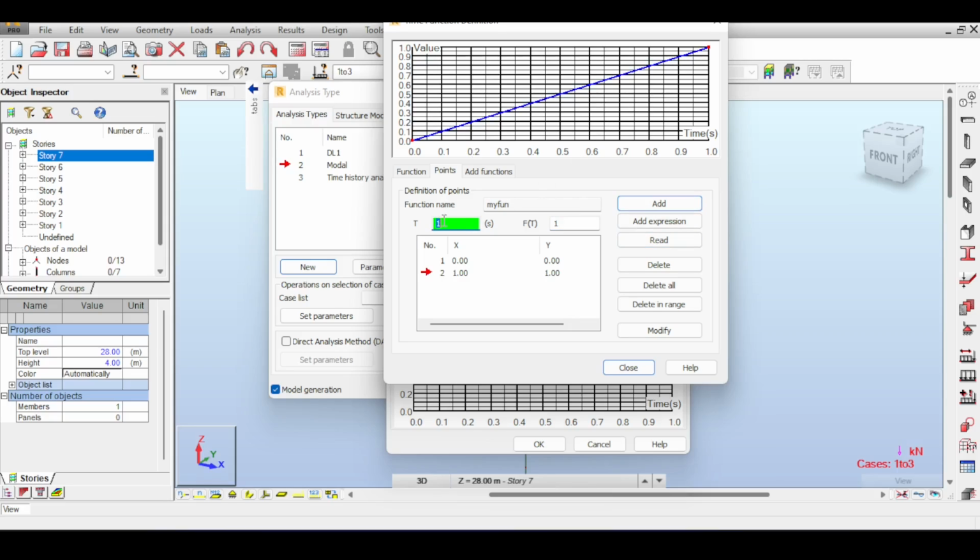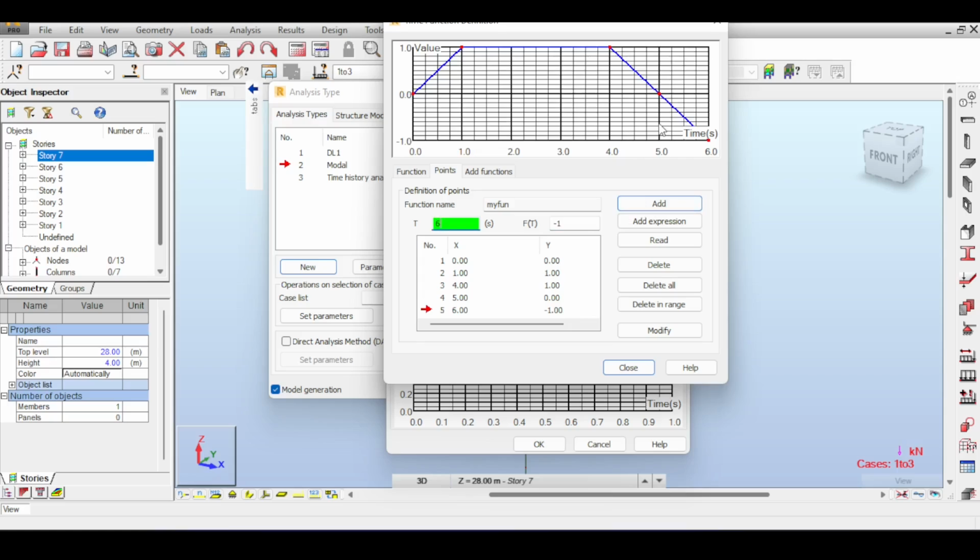For example, I can leave this force for 3 seconds, and then I can eliminate the force at the 5th second, as you can see, by zeroing the force. I can also reverse this process by, for example, reversing this at second number 6, and putting a -1 here. So now you can see that my force is being reversed. And I can keep this force reversed for yet another 3 seconds by going, for example, to 9. And then I can zero the force, repeating the cycle yet again.